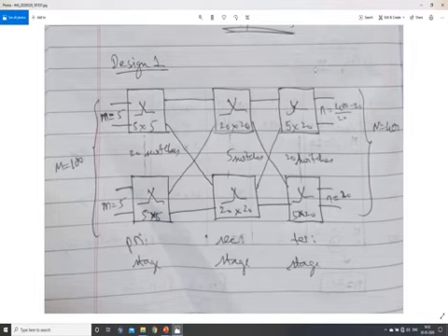But what is the inlet for each of these tertiary switches? This is given by the number of switches which are present, because there should be one link coming from each of the switches. So one link from the first secondary switch, second link from the second secondary switch, third link from the third secondary switch, fourth link from the fourth secondary switch, and fifth link from the fifth secondary switch. Therefore this indicates that the number of inlets is equal to 5.